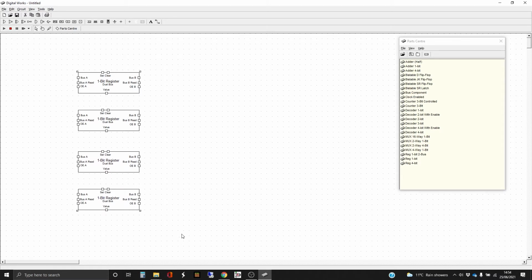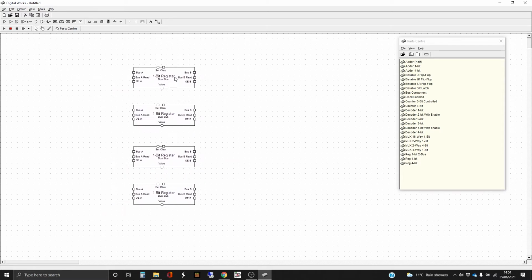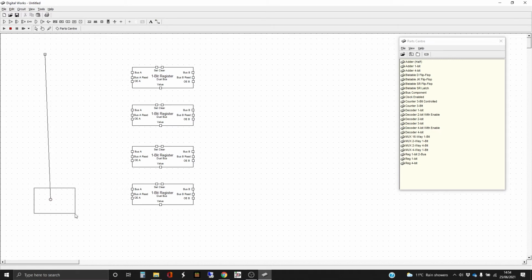Okay, and I'm going to create a bus line, and fairly commonly for me for a bus line, I also put an LED at the far end. It's not going to hurt, or we might not see it unless we need to get in for any kind of debugging purposes.